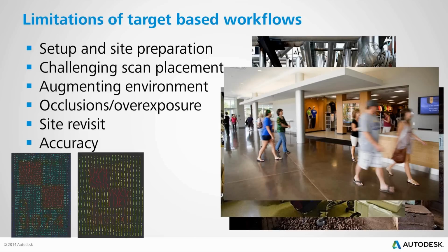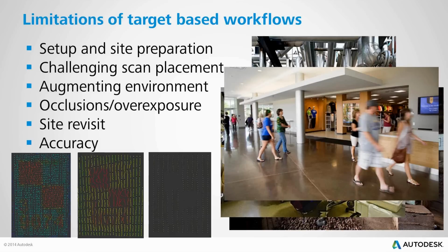And this is at 3 meters, but if you look at that target at 5 meters, it looks something like this. At 10 meters, it looks something like this. And now you can see that it's getting much more difficult to find a very accurate center of that target at these longer ranges. So you definitely need to keep these targets within a certain range for the resolution of the data you're working with. Those are some of the limitations of the target-based workflow.